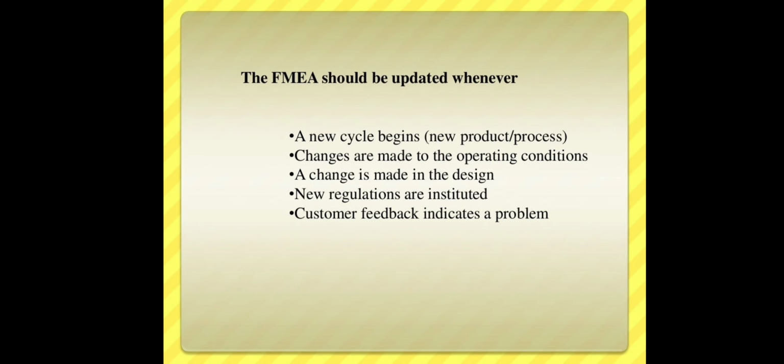FMEA should be updated whenever a new cycle begins, when a new product is started, where applicable, when changes are made to operating conditions, changes are made in the design, new regulations are instituted, or customer feedback indicates problems. We have to apply it in these cases.